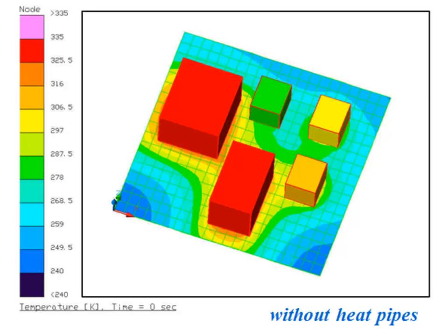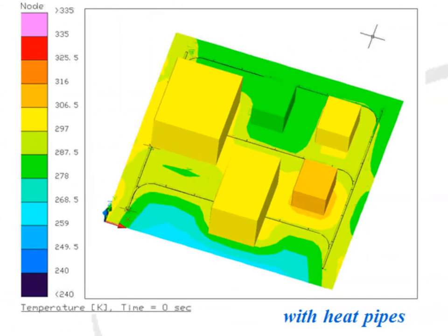In the bottom two graphics, you can see the before and after effects of having added a set of 5 interconnected heat pipes to isothermalize a base plate. The design consists of 3 lateral pipes and 2 header pipes. The heat pipes in this case are actually inside the honeycomb panel, but they've been made visible for post-processing.